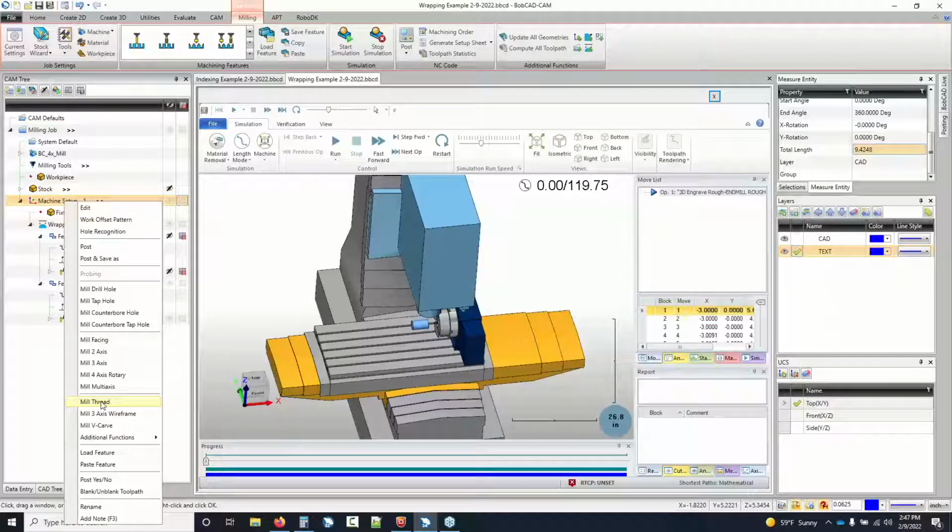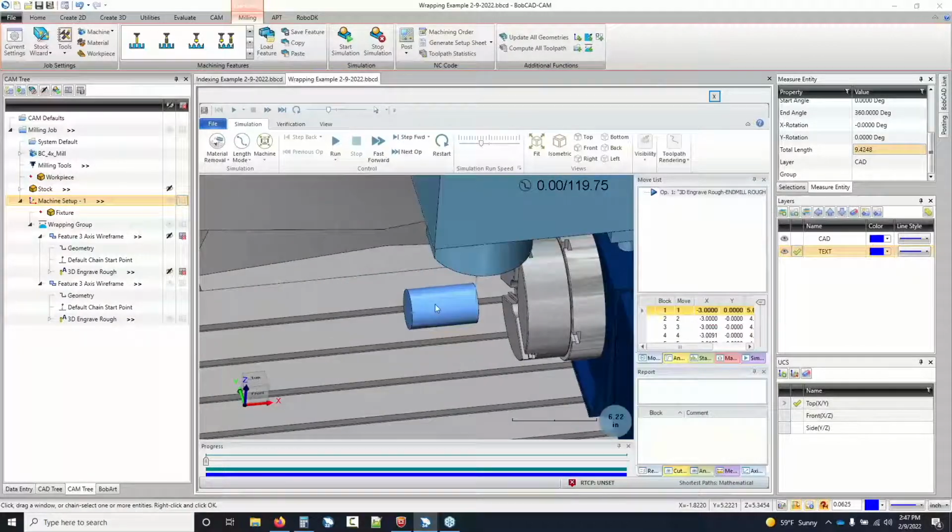But yeah, you could. He used, I want to say, a 60-degree V tool that he slowly worked into the part, just like how this is going to run, except he did multiple passes, and he had the whole thing. It was a much longer part. I mean, you could technically figure it out. You know how many threads per inch you need. So if you're doing a 3-inch wide part, you'd have to do a lot of math for it, is really what it breaks down to.